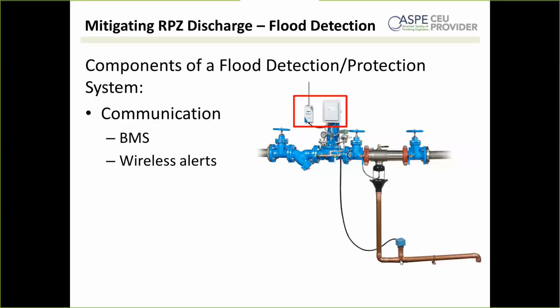You know, you're looking at things like your head loss at a specific flow rate. All of those things come into play when you're deciding on what kind of backflow preventer you're going to get. I will say that stainless steel is certainly increasing every year, right? As a market, more stainless steel backflow preventers get sold and fewer cast iron backflow preventers get sold. So I think that stainless steel really is becoming the future. That's what most people choose to go with.